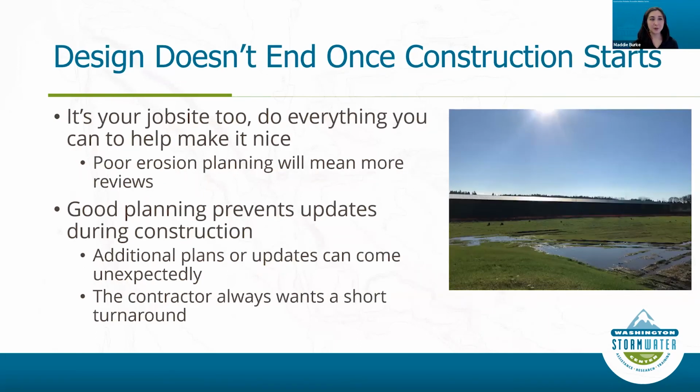So my last point is that design does not end once construction starts. It's your job site too. Your firm's sign might be on the gate. You want to be proud of your site and do everything you can to make it look nice. And if you have poor erosion planning, you're going to have more reviews with the city or county, and more iterations. So it's going to waste time and money.